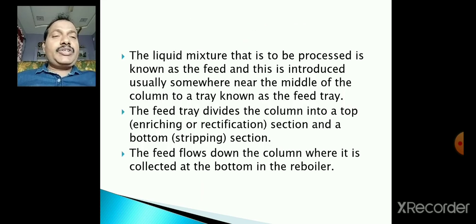The liquid mixture that is to be processed is known as the feed, and this is introduced usually somewhere near the middle of the column to a tray known as the feed tray. The feed tray divides the column into a top section and a bottom section.